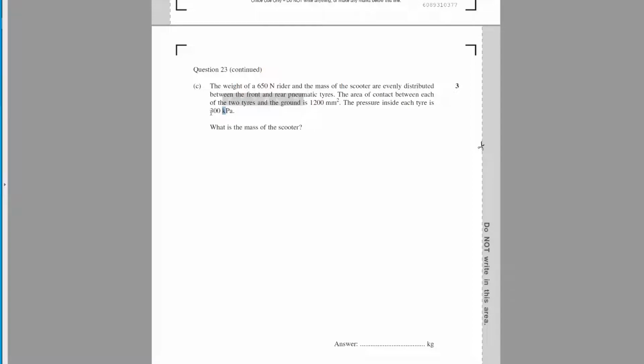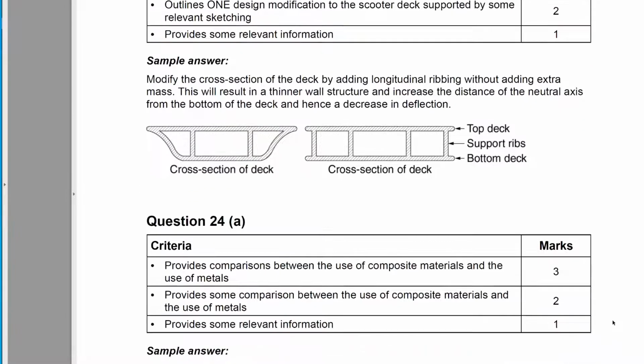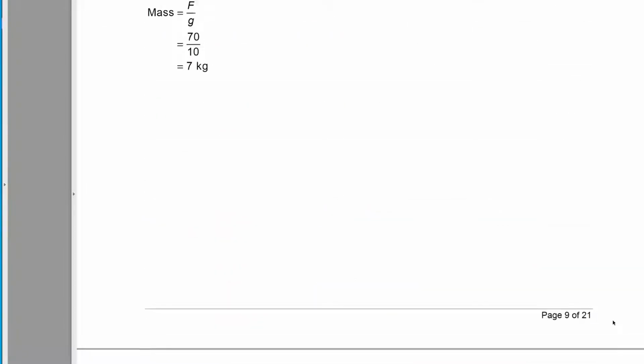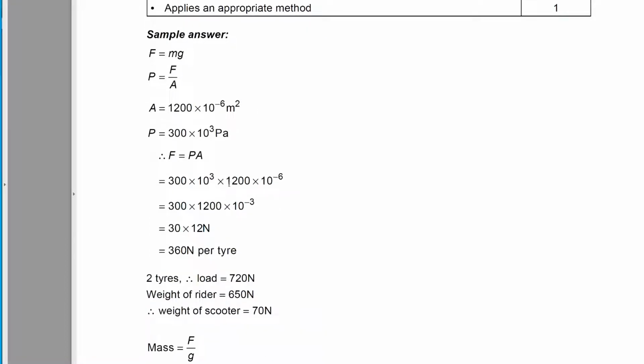So I'm going to say 0.3 megapascals. Tire pressure is usually measured in kilopascals, whereas everything else in the subject is in megapascals. Soil pressure is also in kilopascals. So I would say 0.3, but you notice they've done it in pascals. Good for them, they're smarter than me. Anyway, we're going to get the same answer.